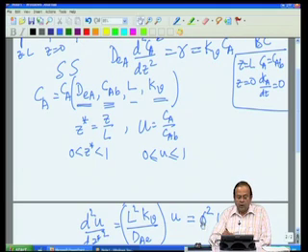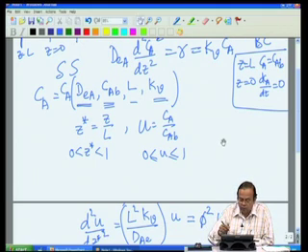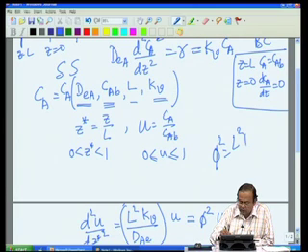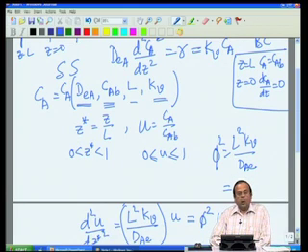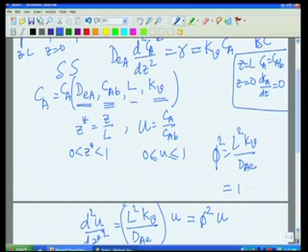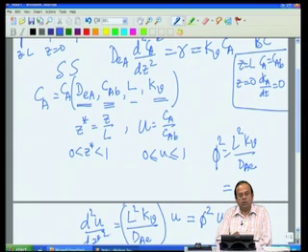Let me write my phi square over here: phi square is L square kV by dAe, let us say its value is 1. If phi square value is 1, irrespective of what combination of L, kV and dAe gave me this value 1, my solution in terms of dimensionless quantities will be identical.